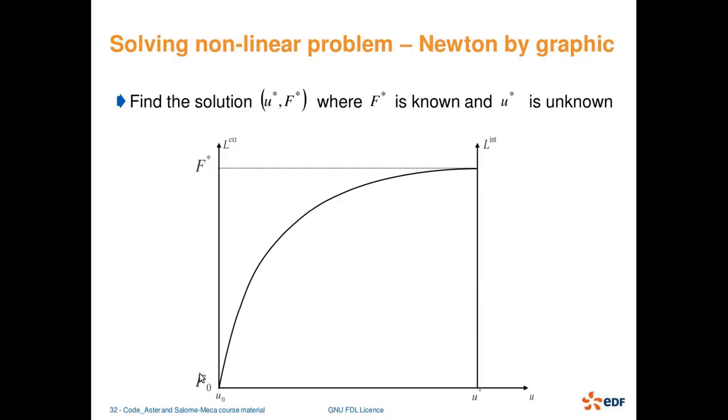So what I have is a load step at time t0, which is f0, and I have the deformation u0, which is known at that time step, all right, and I have another force F star at another time step, maybe T star, and I need to move to the correct solution of the deformation at the next step.